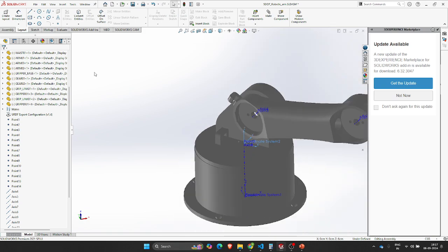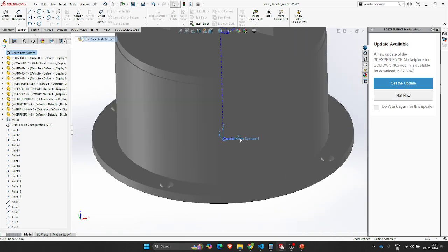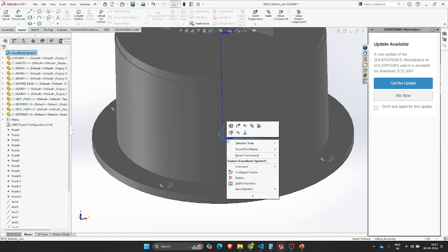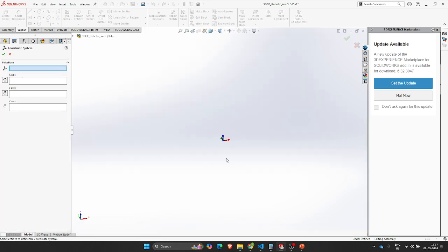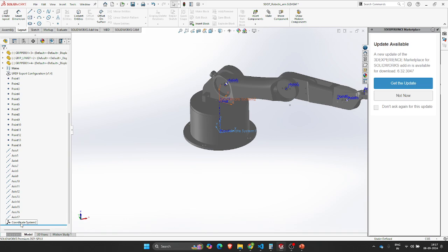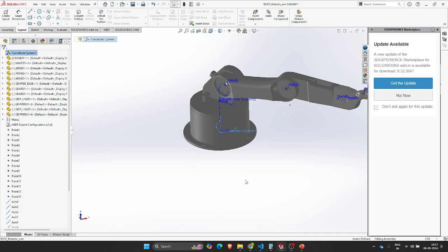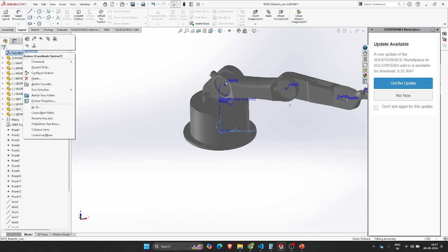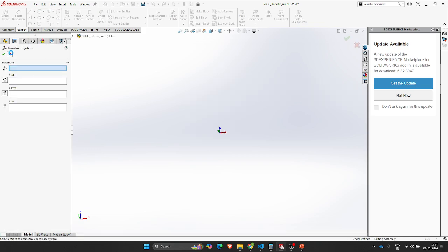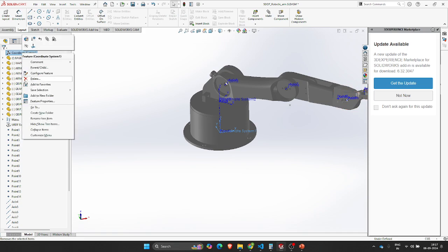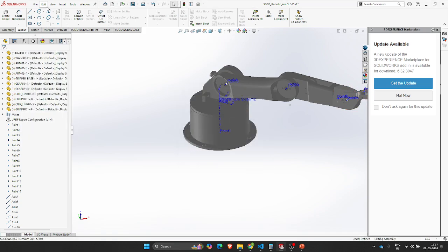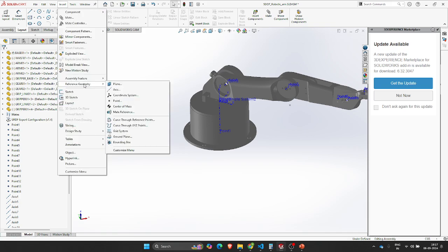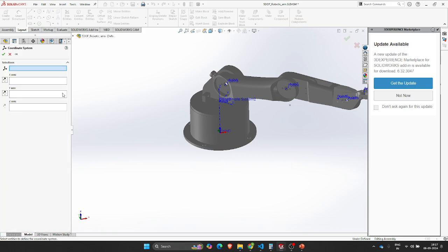And coming back to this, the coordinate frame 2, if we, oh, what happened? Where is this coordinate system 1? Coordinate system 1. So once we try to edit this feature, okay, I would delete this coordinate system 1 for a moment, and reassign this value, align reference geometry coordinate system. Okay, this is good. Z-axis is pointing there, but I want the x-axis once again.